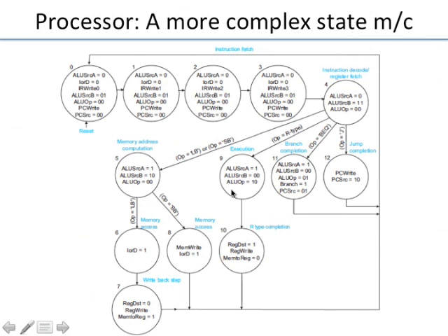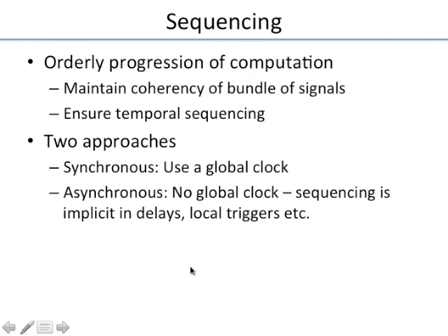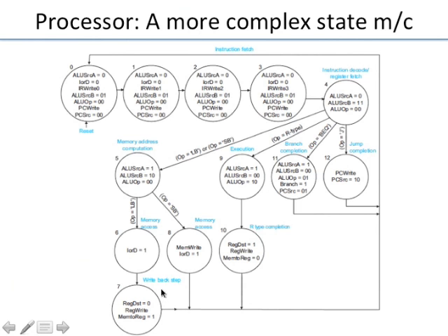Of course, when you execute an arithmetic operation, there could be many possible arithmetic operations: add, subtract, multiply, floating point. You could have all kinds of complex arithmetic operations. But at a higher level, these are the 4 in this particular processor. So if you come to the memory, again you can have either a load or a store, and then based on load or store, you decide to activate certain signals, and then you complete it.